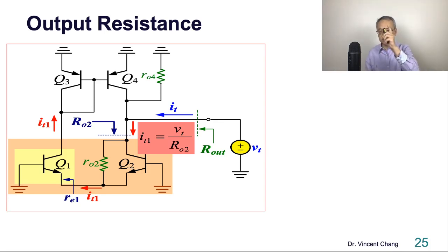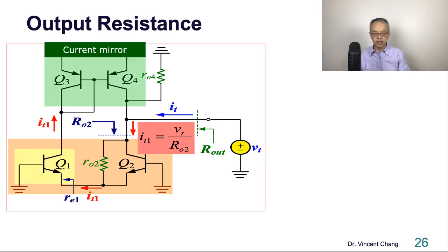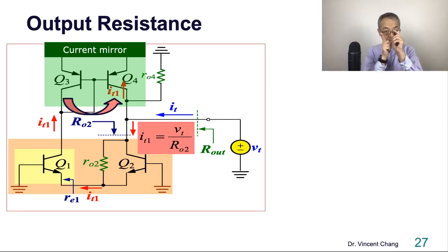Once the IE1 touches the current mirror, on the first order level, ideally, you would reproduce another current on the right-hand side, IE1. But this is the ideal, the first order. I said my word very carefully. First order, but you need to consider second order, channel length modulation effect, the output resistance.